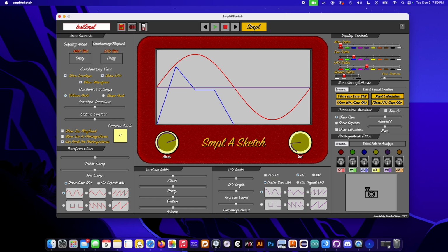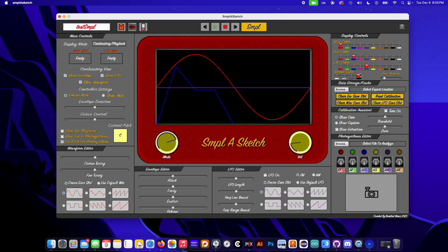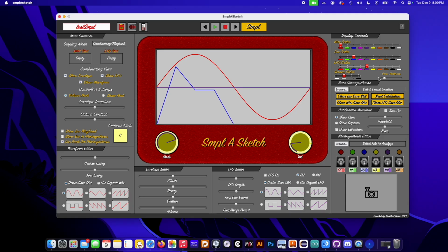And let's say, hey, this screen is kind of hard to read these waveforms on. I want the screen to be fully white, or I want the screen to be darker, either this darker gray or this black color. You can change that there too. Or you want to say, hey, I can't see the waveform, so I'm going to make the lines a little bit thicker, which we could do by dragging the slider. So yeah, that is all of our main display controls.